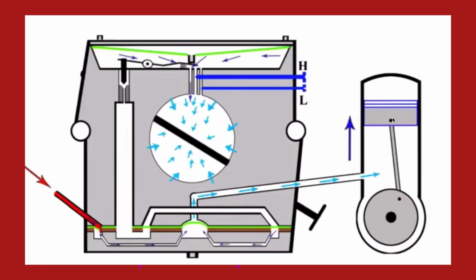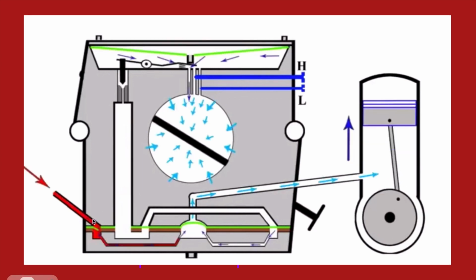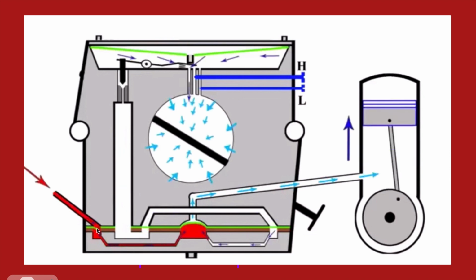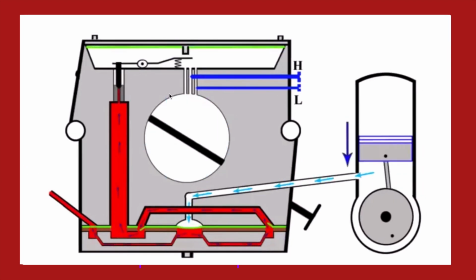On the upstroke of the piston, the negative pressure in the crankcase causes the diaphragm to balloon upwards, creating a negative pressure zone. This closes this one-way valve and opens this one, allowing fuel to flow in. Once we reach the next cycle, more fuel flows in. However, on the downstroke, the positive pressure causes fuel to be pushed back and stopped at the one-way valve. In the next cycle, we see that fuel can finally be pushed through, and fuel eventually reaches the needle valve.